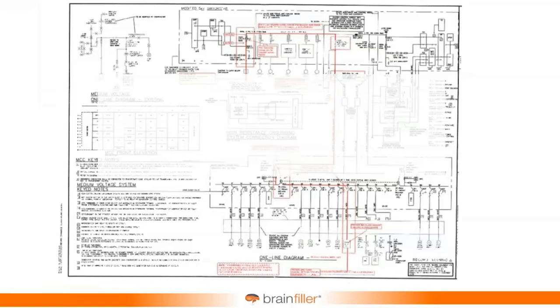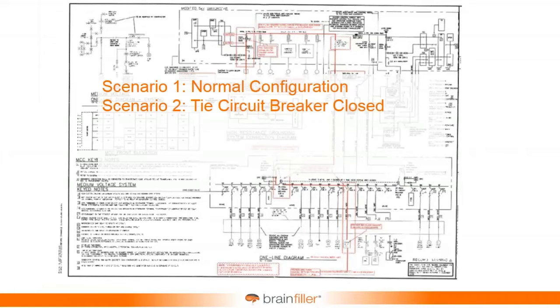And suddenly the question becomes, well, if I'm going to perform arc flash calculations, of course I want to base this on the normal configuration, the normal short circuit current, the normal configuration of ties open or closed or whatever you happen to have. And then alternative scenarios or alternative configurations, maybe the tie breaker was normally open, and now what happens if it's closed?